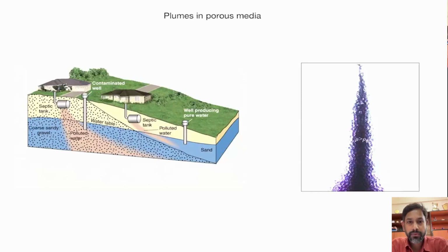where in molecular diffusion we consider there is absolutely no flow, and mixing between contaminated fluid and the fresh fluid is happening just because of diffusion, whereas when there is a background flow in the water, then that background flow actually enhances the rate of mixing, and that mixing we call mechanical dispersion. And we have seen both the cases, but in case of mechanical dispersion we considered the velocity to be uniform, right, constant everywhere, so that we did not consider the effects of changing velocity, and we only used the advection dispersion equation to model our mixing behavior.